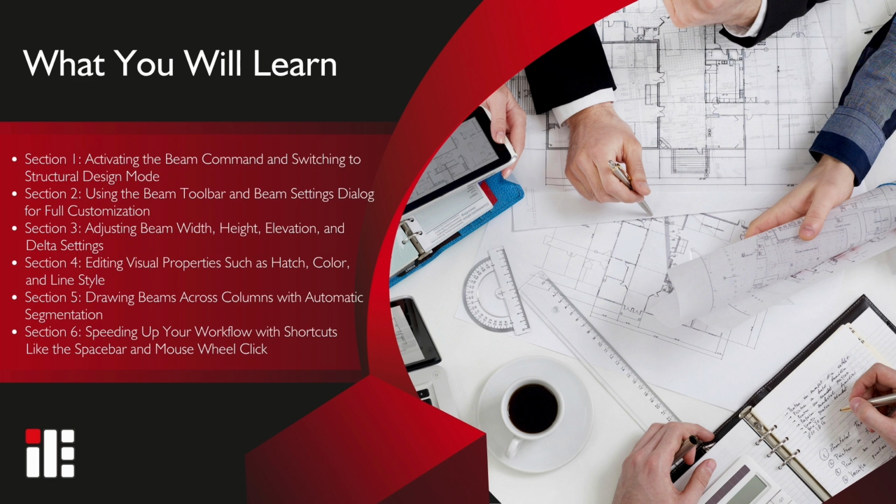In this video, you'll learn how to create concrete beams as part of the structural formwork plan in ideCAD Architectural. We'll show you how to activate the beam command, work in structural design mode, and use the beam toolbar to define width, height, elevation, and delta values.